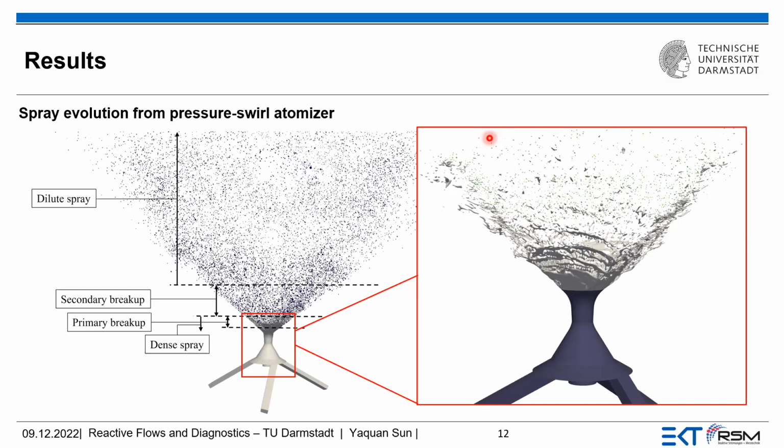Okay, one more thing. Is there any possibility to design a swirl injector for PFI below 5 bar? It's just a question that hit my mind. If we can design something for below 5 bar, a swirl kind of injector, will it help in reducing the SMDs?